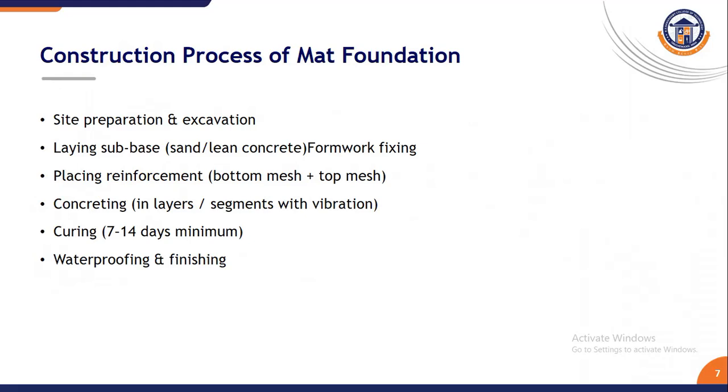Then curing for at least 7 to 14 days to gain strength, and finally waterproofing and finishing if required. So these are all the construction processes of mat foundation.